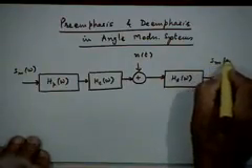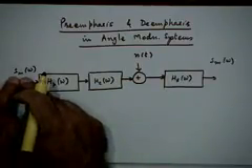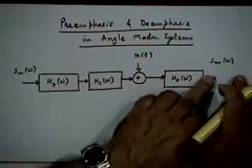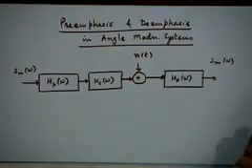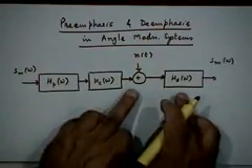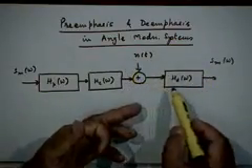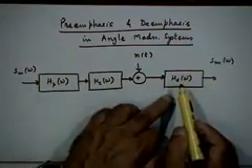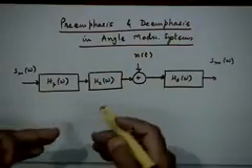Finally, as far as the message is concerned, if it has a certain power spectrum shape at the input to the system, you must have the same power spectrum shape at the output, so that the message signal remains undistorted. In the process, the SNR performance of the output can be improved if you choose your pre-emphasis and de-emphasis filters appropriately. I want to discuss very briefly what kind of optimization you can do in the choice of these filters to improve the output SNR.